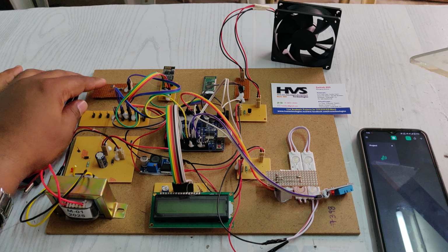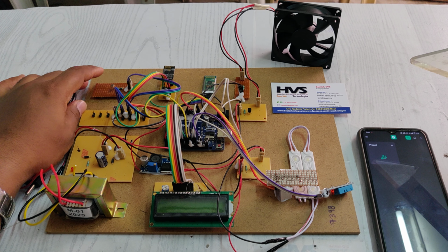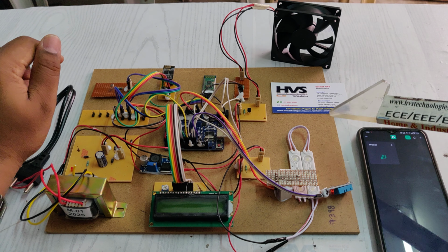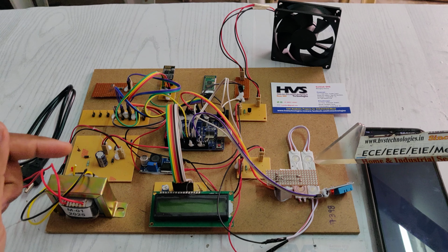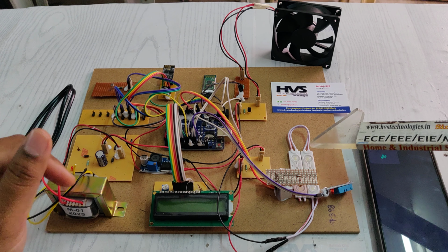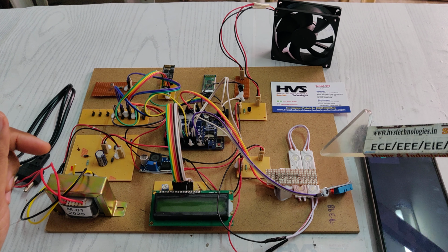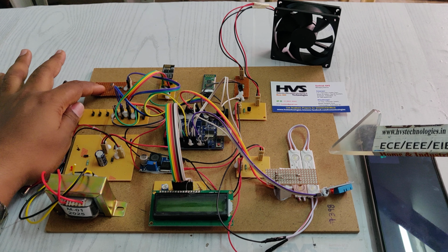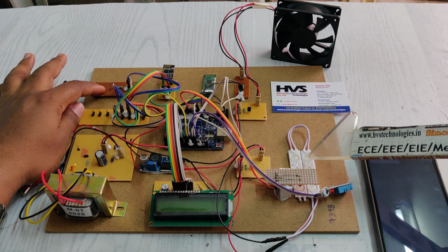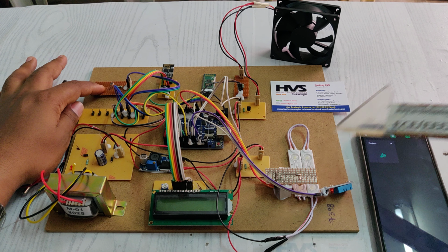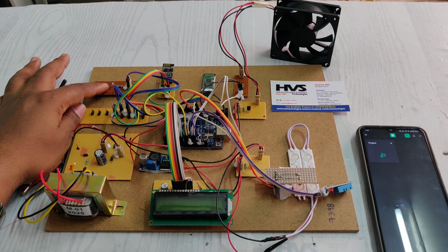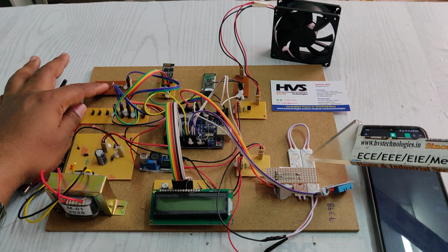Whenever darkness is detected, which is identified with the help of this LDR sensor, only then will the light switch on. Before that, the user has to provide the instruction to turn on the lights. Once the user turns on the lights, based on this LDR sensor, meaning the light intensity, the light will keep switching on and off continuously. And when we turn it off, irrespective of the LDR input, the system won't control this LED.